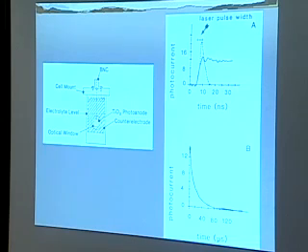And even if you had a faster pulse, it wouldn't really matter because you have an RC time constant, which you don't have in normal photochemistry, and you're not going to go any faster than the cell's RC time constant, and that's going to be more on the microsecond time scale no matter what you do. So that's the first complication. We have to deal with the RC time constant.